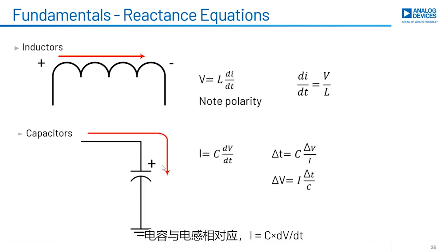For the capacitor, that's kind of the counterpart to an inductor, I equals C dV/dt. And if we remember that hot plug example where the current went through the roof when we hot connected it, this equation is why. The voltage changed by 12 volts in 10 microseconds.